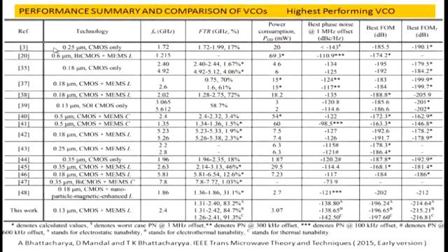I compare with all the results to date. Look at this work. The phase noise performance is unbeatable: minus 138.8 dBc at 1 megahertz offset, which is a world record till now, published in 2015 in IEEE.